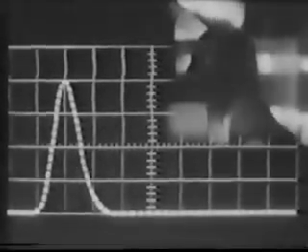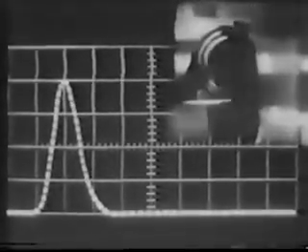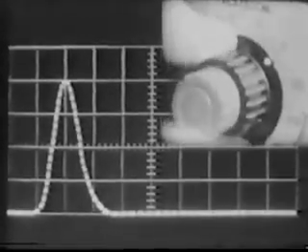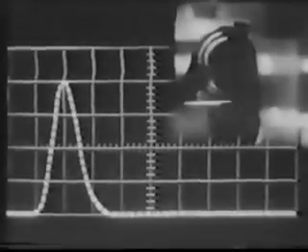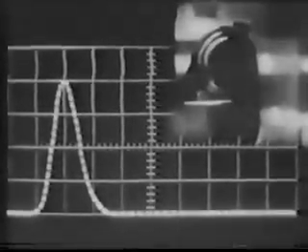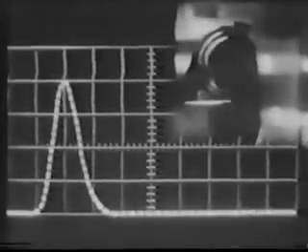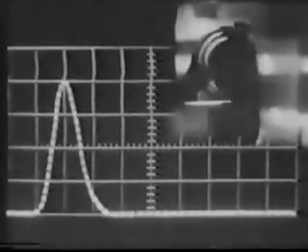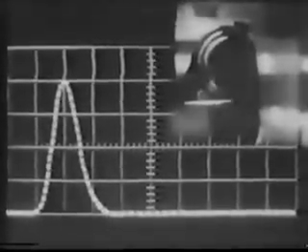The resulting pulse height has fallen to 2 units, but I can raise it to 4 units again by doubling the gain of the oscilloscope. Now you can see that the hole pulses that are 4 units high coincide at all points with the pulse for full light intensity. This coincidence of the pulses shows that the oscilloscope deflection is proportional to the hole concentration under the detector.